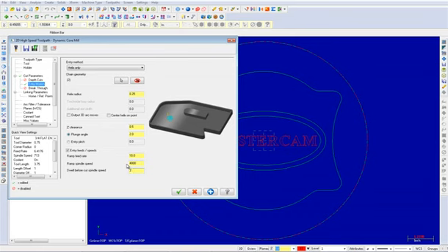I will now explain a few of these parameters. Entry method defines the entry point and cutting strategy used to create the toolpath. Z clearance adds an extra height used in the ramping motion down from a top profile. It ensures that the tool has fully slowed down from the rapid speeds before touching the material.